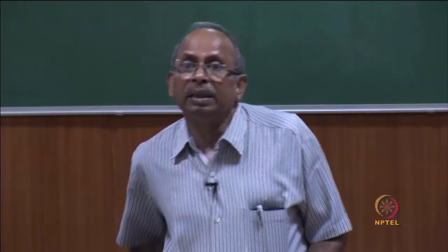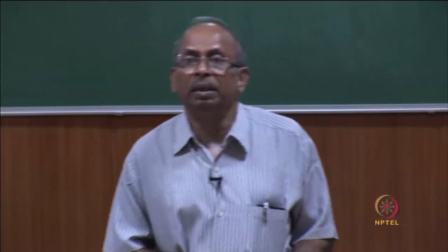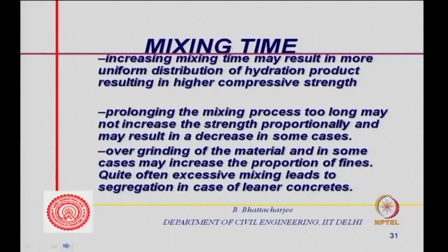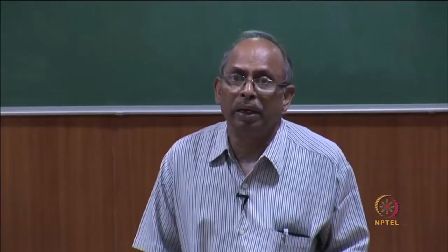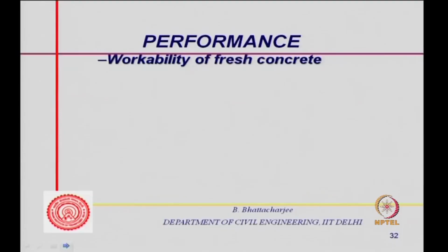Quite often excessive mixing leads to segregation in case of leaner concretes. So, mixing time should be optimal, not too high. We will come to this mixing curve a little bit later, but just look at the performance of the mixture.